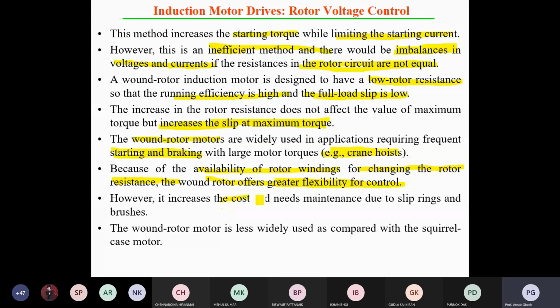Now, power electronics control, which you know as a very common feature from any of the drives books. Slip control of the DC converter, so slip power recovery. You get the pulse DC bridge, which is uncontrolled; it may also be changed to a controlled bridge. A smoothing reactor is there, ID, and you can do GTO based controlling. So you can get the VDC value.